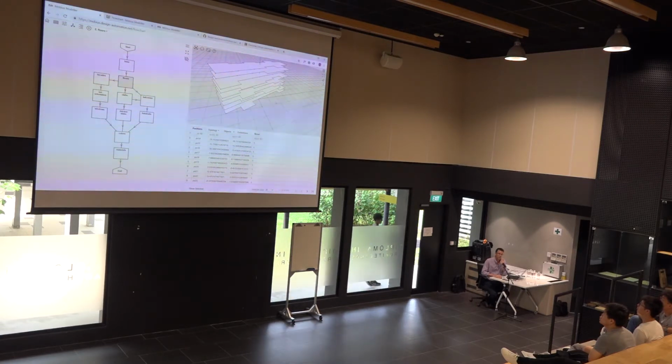So we don't want to immediately add handrails and all that stuff, because if you add too much information on this level, then in the nodes further down, you're just going to be struggling to ignore that information. Like if you've got handrails in the first node, then in the second node, you're going to have to do something where you don't want handrails, and then you have to try and delete the handrails and all that. So you want to keep it very simple at the top nodes and gradually get more complicated.